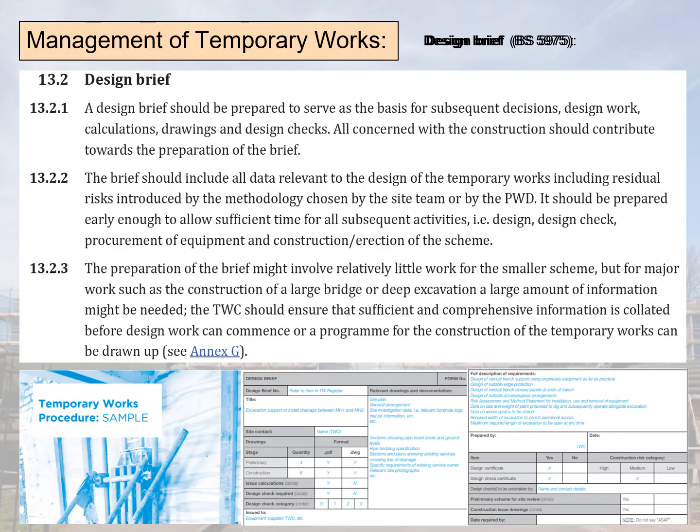When looking at the management of temporary works, one of the first things we will produce is the temporary works brief. The design brief should be prepared to serve as a basis of all decisions, design works, calculations, drawings and design checks. It will include all the permanent works design elements to enable the temporary works designers to incorporate them into his decision making. All parties concerned with the construction activity should contribute towards the preparation of the design brief. This includes subcontractors, the principal contractor and the principal designer.